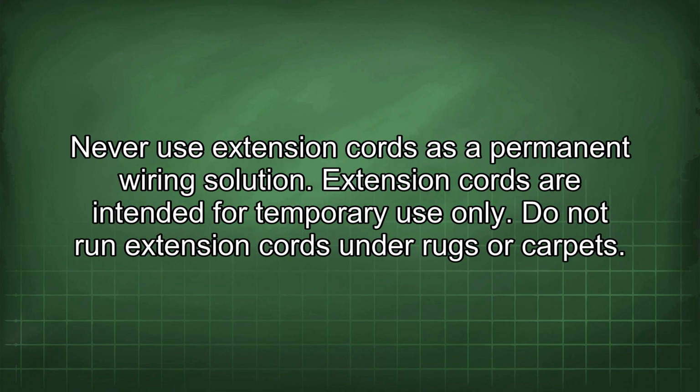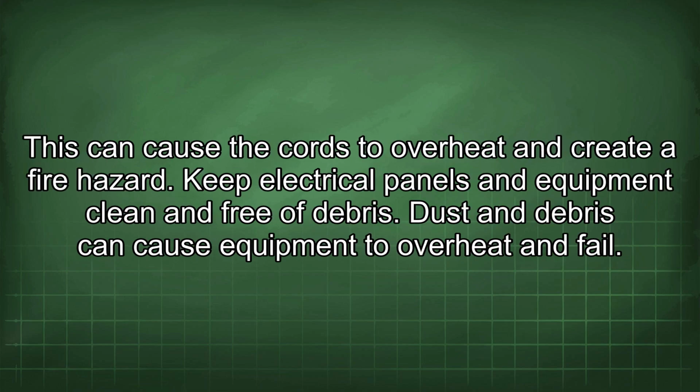Never use extension cords as a permanent wiring solution. Extension cords are intended for temporary use only. Do not run extension cords under rugs or carpets. This can cause the cords to overheat and create a fire hazard. Keep electrical panels and equipment clean and free of debris. Dust and debris can cause equipment to overheat and fail.